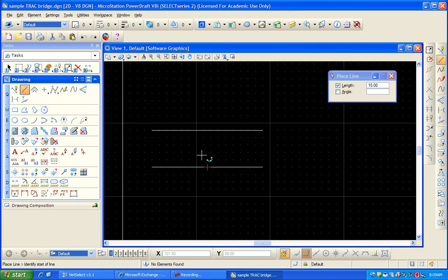I want to offset a line 4 inches on either side, which will give me 8 off the midpoint. To do that, I'm going to check down to my snap tools, which I said are important for drawing things out right. And I'm going to make sure I have the midpoint snap on.